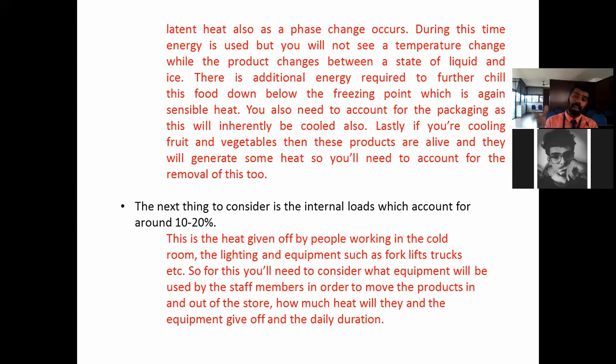Now it will be coming again sensible heat. Why? Because there is no phase change. In order to convert the liquid into ice, there is a phase change. At the freezing point, if you are further freezing, ice will remain ice only. There is no phase change, so again we need to calculate only the sensible heat.